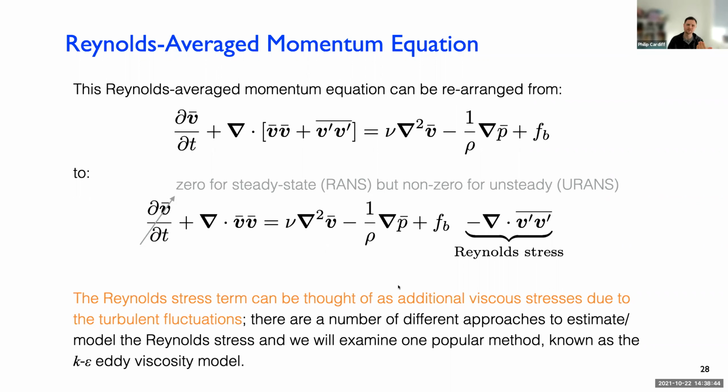If you go to a laminar region and then suddenly go to a turbulent region, because of all the mixing, it apparently seems like it's more viscous. The true viscosity of the fluid is the same, but if you're not directly modeling those eddies and you just have a coarse mesh and you're trying to account for the effect of all these small eddies, it's like an increase in viscosity in those regions.